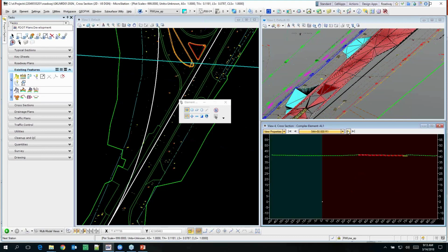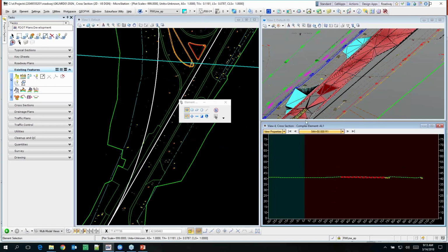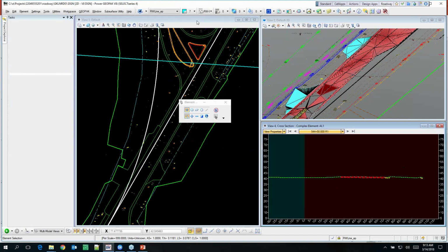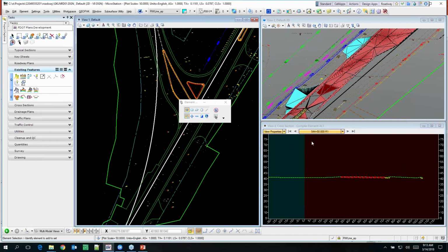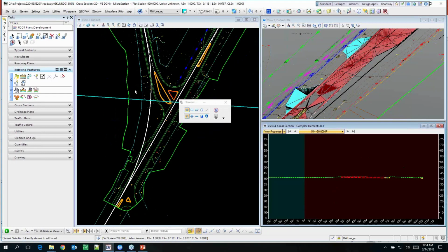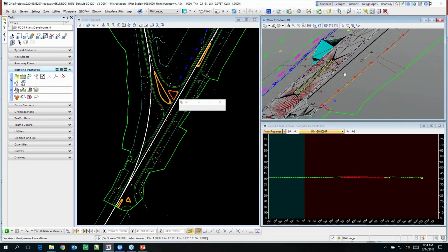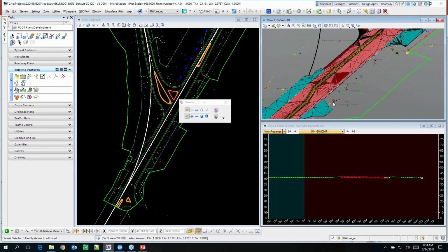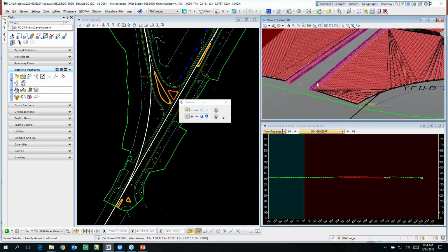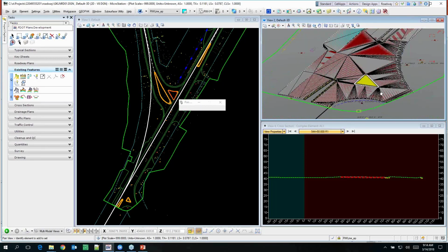Yeah, so most of those tools are not going to work because it's an alignment cross-section view. That's right. Thanks for reminding me, we'll demo those a little bit more when we get to those features. This is setup. This is necessary, but it's also a little bit tricky. But it's just the main concepts. Get those shapes, close the shapes, and then you can add surface templates for your pavement, and then later, once you know how to do corridors, you can add a corridor for the curbs, and those are kind of the overall concepts. So everything shows up here.